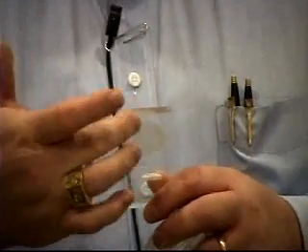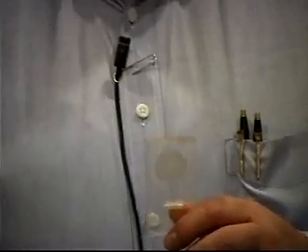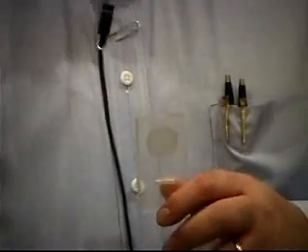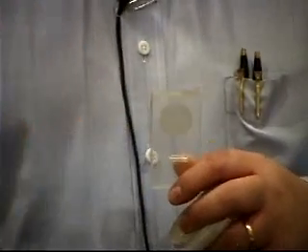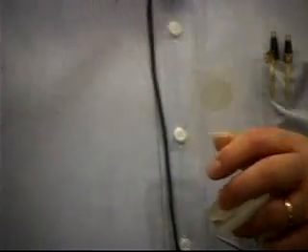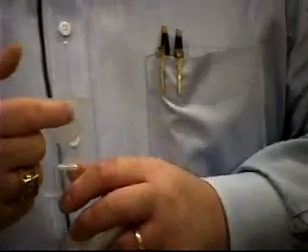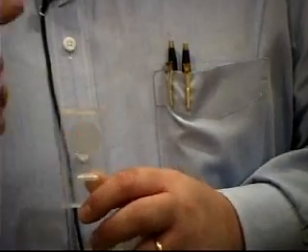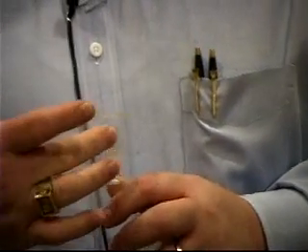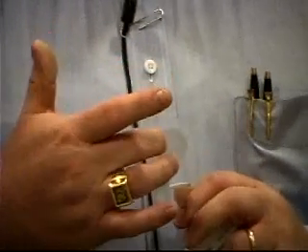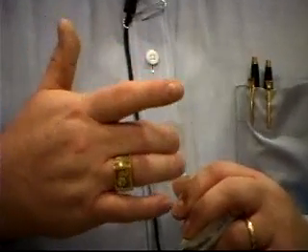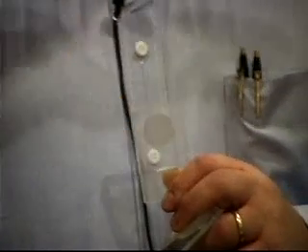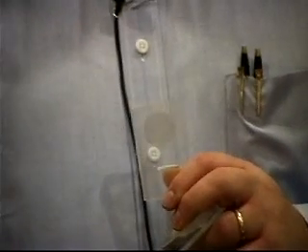It turns out the beam is generated in a circular annular tube, or a circular tube of gas, and this is what's called a fast axial flow, because you've got to cool the gas, so you just pump it down the pipe. And as a result, you get what we call multimode effects. You actually get diffraction spots. So if you feel the surface, you can see it, but you can also feel the spots on the surface. This thing is kind of bubbly, or has little bumps on the surface. And those are diffraction spots from the multimode of the laser.